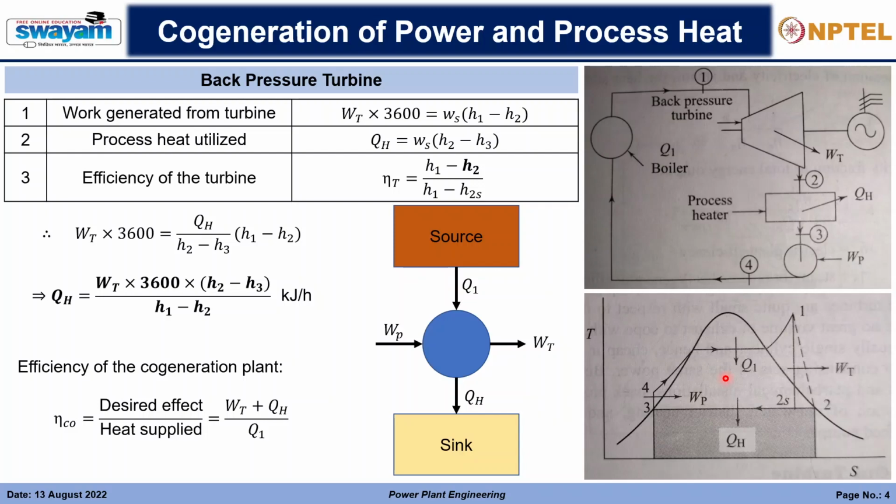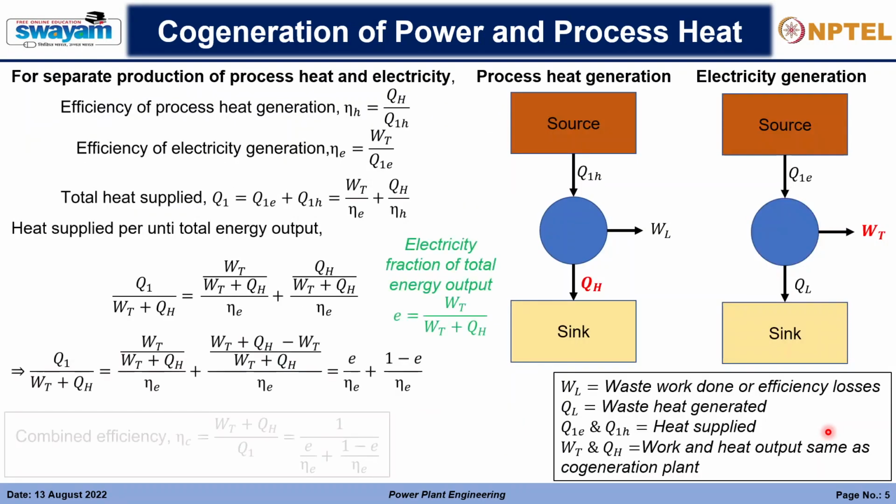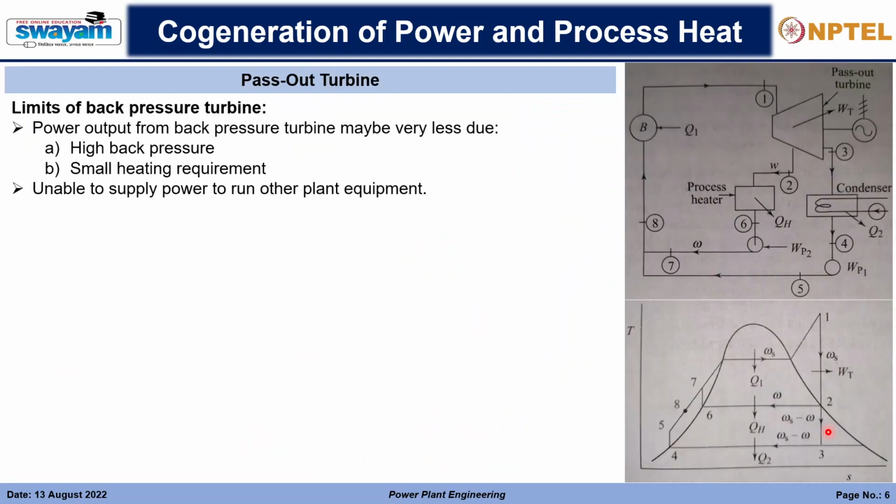Now in this case, the full potential of the turbine was from 1 going to 2 dash, somewhere like here. So this is an intermediate pressure, but the lowest pressure was still here. See, here what we did was that we did not stop the pressure at the exit of the turbine at point 2, but we allowed the steam to expand a little bit more till the low pressure of 3. So that is the full potential of the turbine.